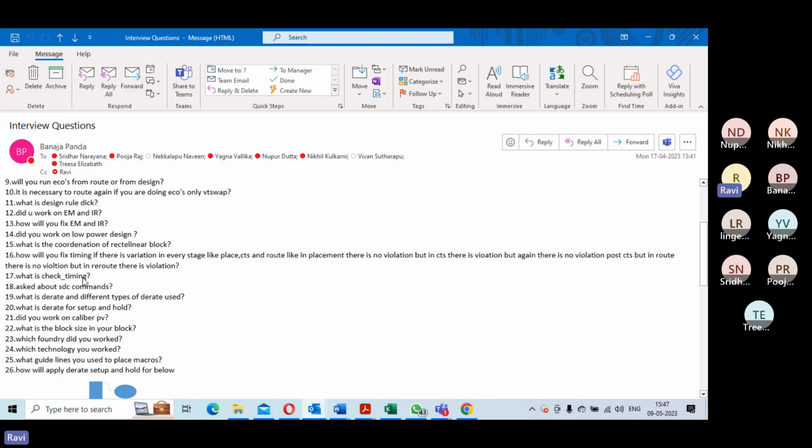So when you say create clock, what all aspects you have to specify? Create clock, hyphen name, you will have to give a clock name. You have to specify the period, and the port name on which you want to define the clock, port or pin name. And either you'll have to define a waveform or period, right?